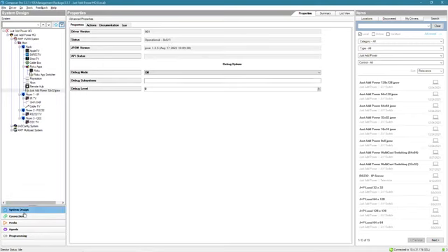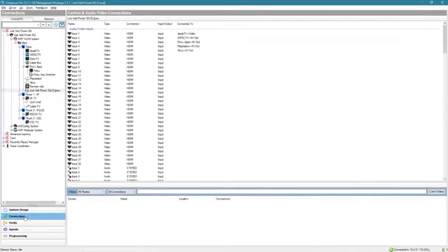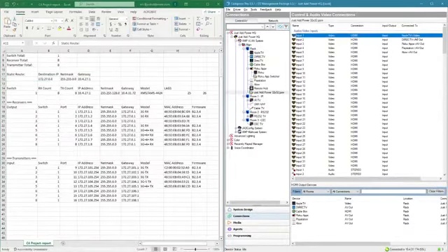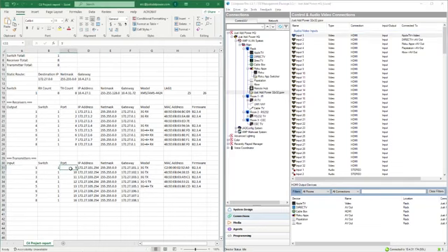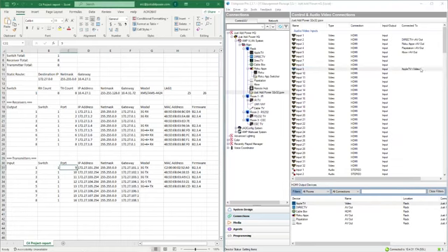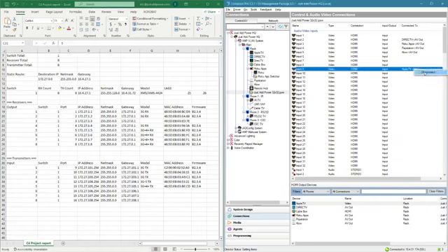The second most common mistake we see on Control4 when doing this is that the inputs and the outputs are bound incorrectly. A common mistake is input 1 here is an Apple TV, but our first input is actually on port 9. So what we'll see on accident is we will see installers want to put the Apple TV on input 9 because port 9, they think input 9, which is an understandable mistake.